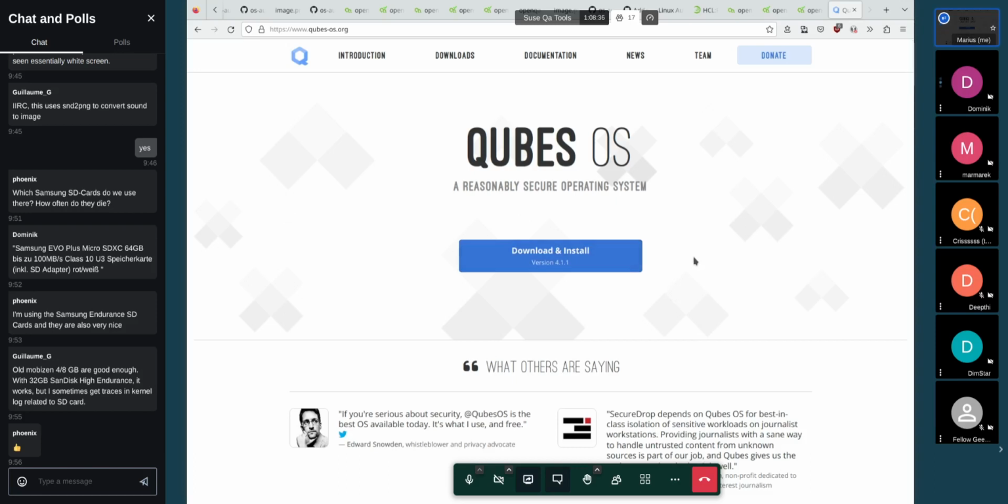With the QEMU thing, I might mention one thing. At least for Raspberry Pi tests, they run better on real hardware. They run in QEMU, and we do some tests, but the real hardware tests actually are more stable than the other ones. Which is, I think, not only related to typing issues, but also because the environment that QEMU emulates is still a bit different than the real hardware, which is why I'm testing on real hardware, seeing that Wi-Fi and Bluetooth and all the other I/O works.